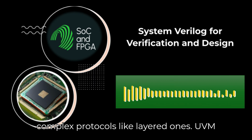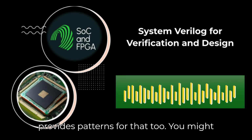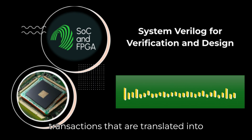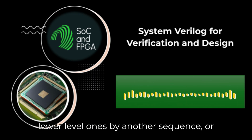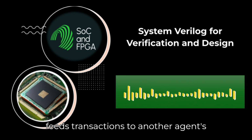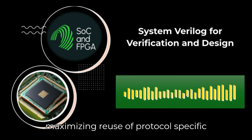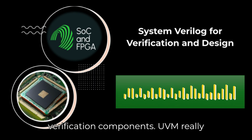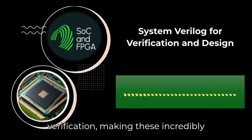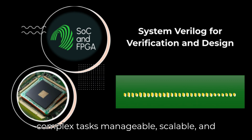And handling complex protocols, like layered ones, UVM provides patterns for that, too. You might have layering sequencers, where one sequence generates high-level transactions that are translated into lower-level ones by another sequence. Or layering agents, where one agent's monitor feeds transactions to another agent's sequencer. The goal is always maximizing reuse of protocol-specific verification components. UVM really provides a kind of design pattern for verification, making these incredibly complex tasks manageable, scalable, and much more efficient.